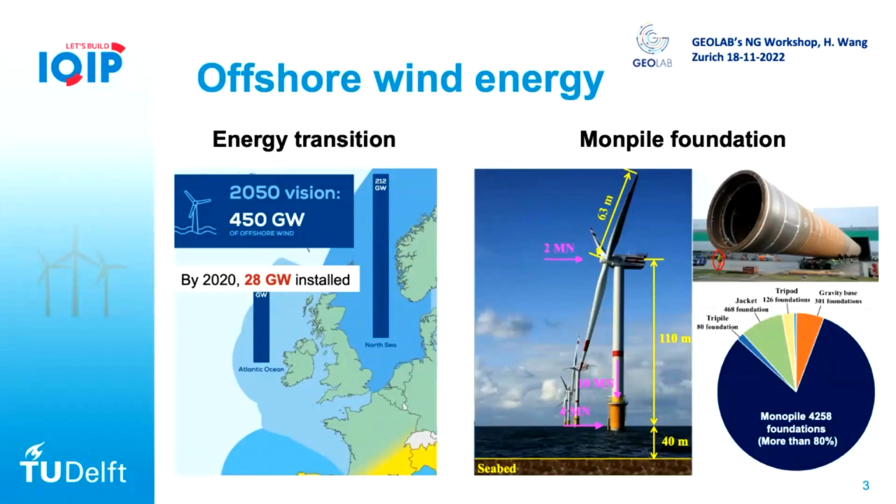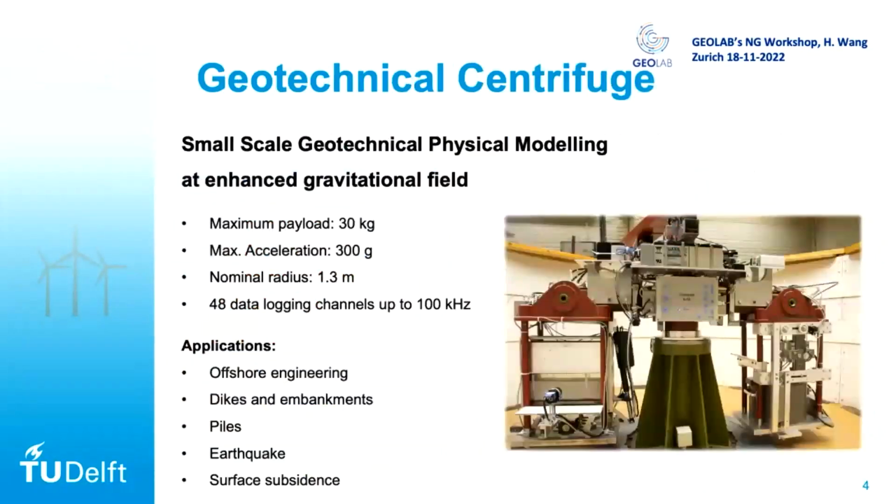foundation. And as you can see here, the monopile foundation for offshore wind is subjected to large cyclic load from the environment, like wind, wave, and currents. And also because the offshore wind turbine is quite unique, it's a very long, tall, slender structure. So we have very strict design requirements for the dynamic behavior of the structure. So we really need to know what the foundation stiffness is at very, very small deflection. And all the work was performed using the centrifuge at TU Delft.